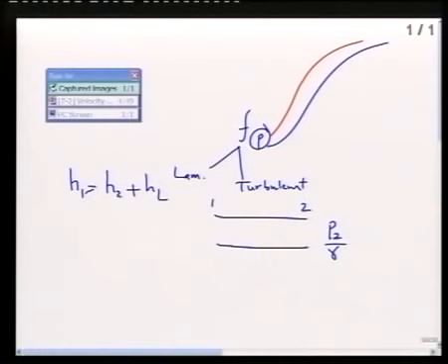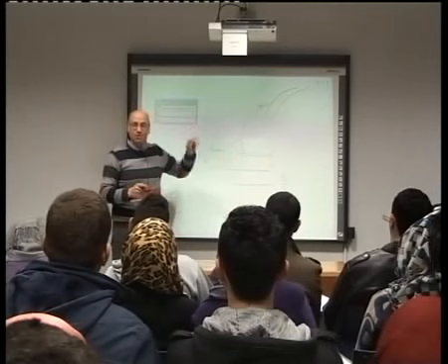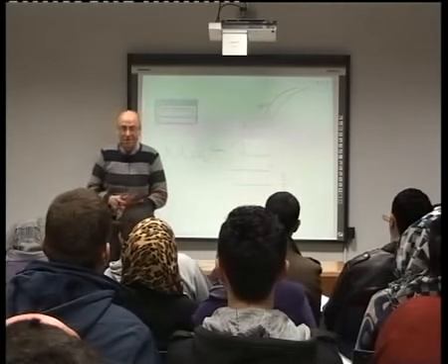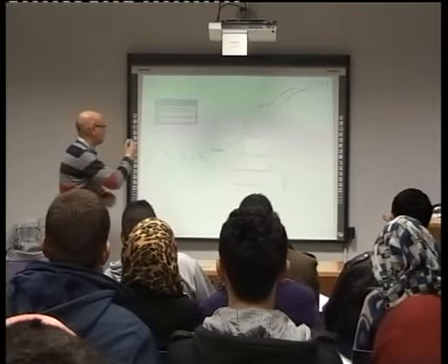You must know the head loss through the pipe in order to know what is the right capacity of the pump. So this will help us to choose the right pump. So this is the way to say it, not like what you have already said.